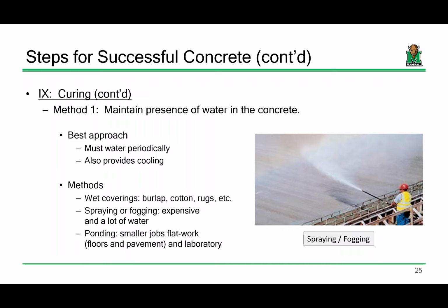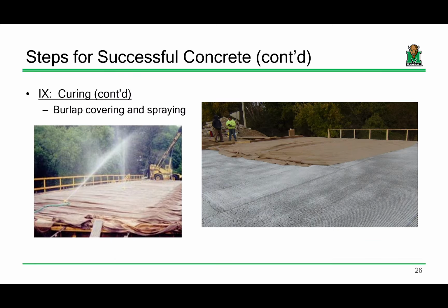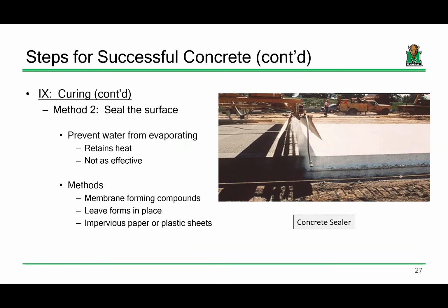escaping. You'll also probably cover it with a fabric, like wet burlap. I imagine that's been done on a lot of the projects you've been working on. They'll cover it with burlap or some sort of cotton type material that's damp to keep the moisture locked in. This was what it was like out on the Iowa project I was on after they sprayed the deck. You can see the white goopy stuff they sprayed. They then covered it with burlap and soaked it in water to ensure that it cured properly.